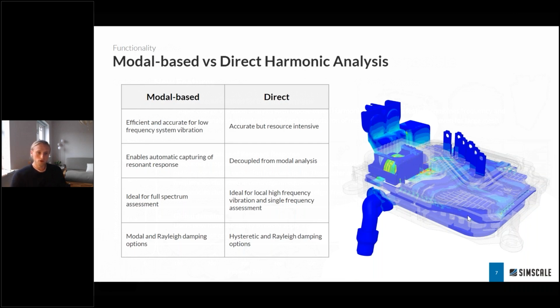On the other hand, with modal-based analysis, rather than using the nodal degrees of freedom to describe the dynamic response, the dynamic response can actually be described as a combination of the eigenmodes and the eigenfrequencies of the model.